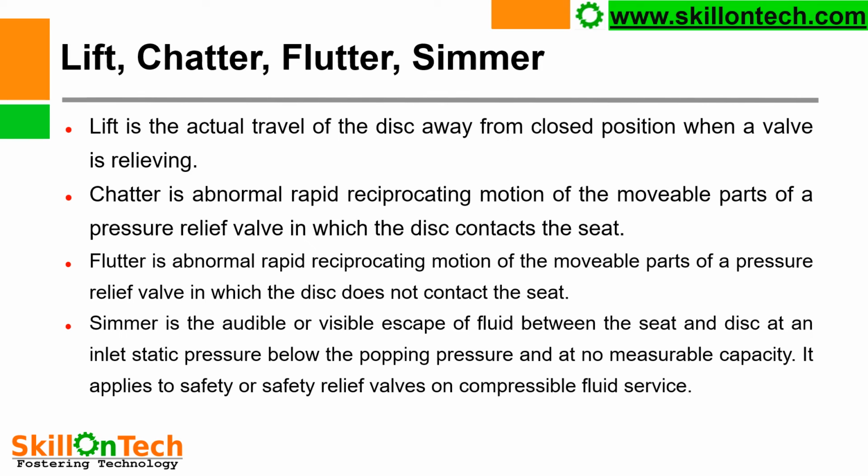That is called flutter. Simmer is an audible or visible escape of fluid between the seat and disc at an inlet static pressure below the popping pressure. When the internal pressure is increasing and it is trying to reach the set pressure, but just below the set pressure, the disc will start to lift, and that is called simmering.